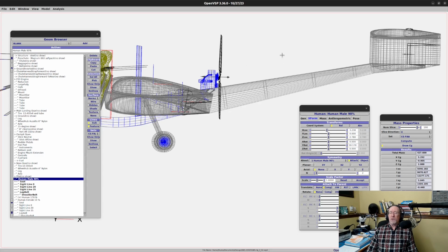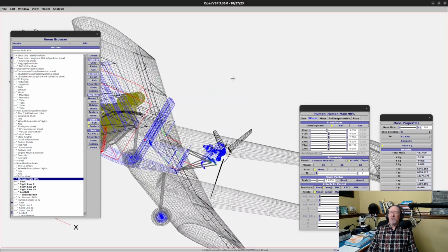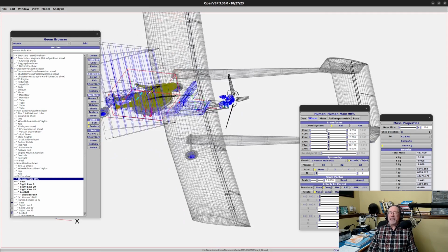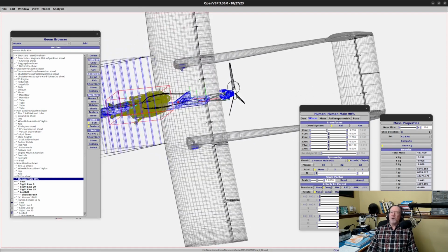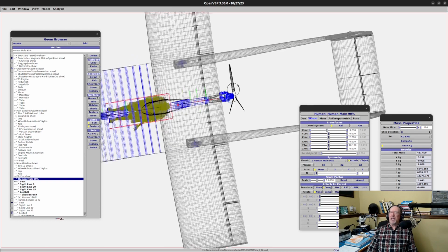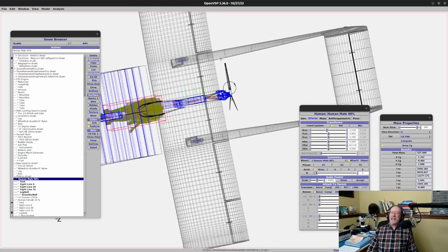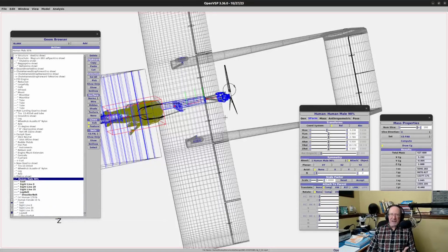The width probably won't change, and that's because of where the booms are. I want this airplane to go into an 8-foot wide trailer. So from the outside of the boom and outside of the tail is 7.5 feet. So I can just barely get into an 8-foot trailer, at least most 8-foot trailers. So that's not going to change. Width probably won't change. I guess it could be narrower, but I don't think I'll do that. What I would like to do is retain my 72 inches of width here between the booms, just in case I can find a larger diameter prop. I don't think it's going to happen, but I want to leave myself that option.